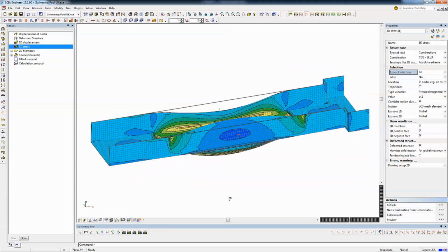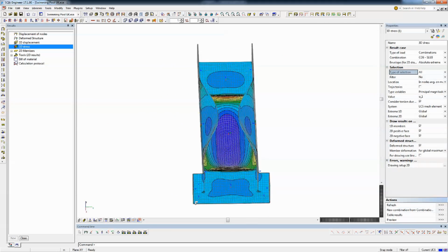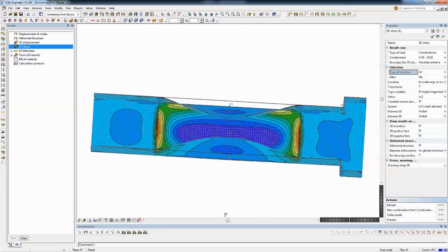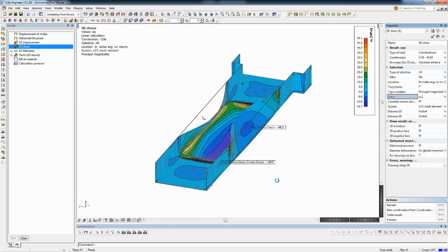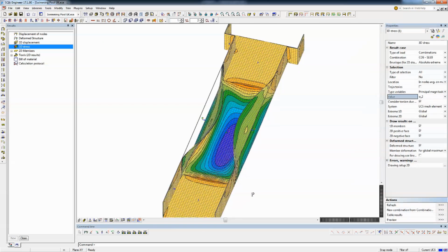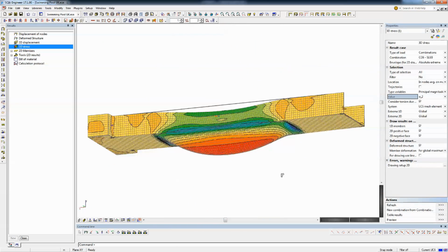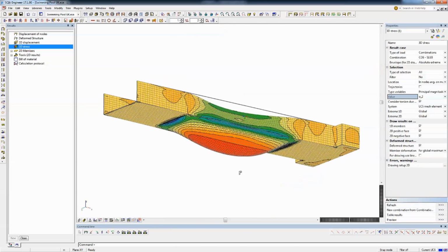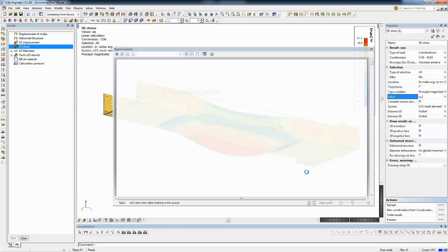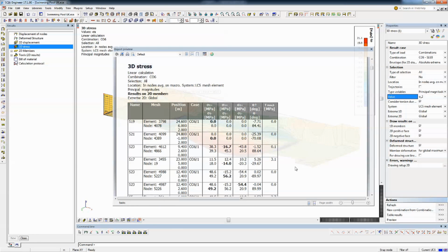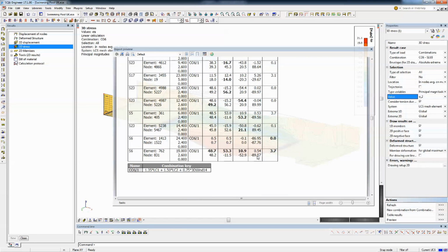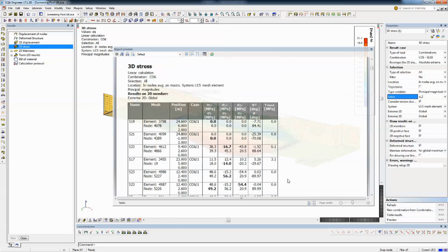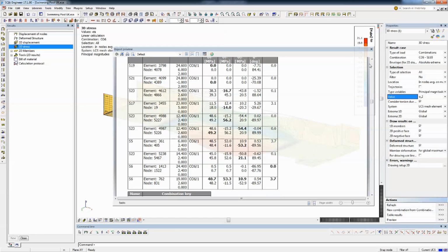Although it's a single layer shell, I use the effective thickness calculated with that converter that I presented before. That converter offered me the solution to know what the effective thickness is. And then I can do the unity check. So aside from looking at the stresses and thinking of myself opening an Excel and determining the capacity, we can just use the functionality in the software to determine the capacity based on our additional input.